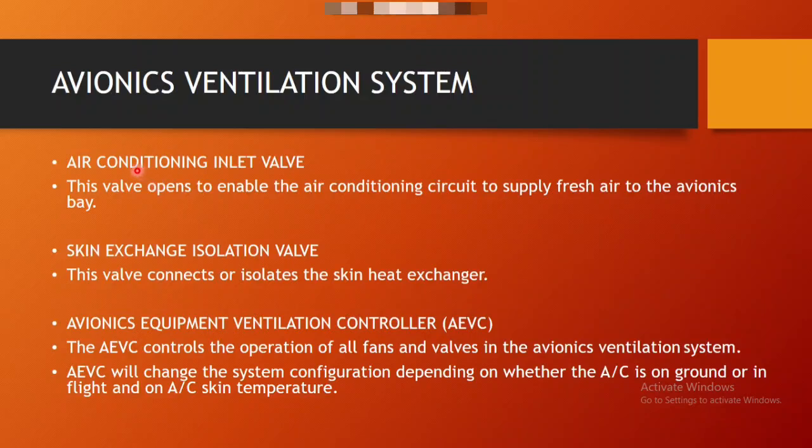Another is the air conditioning inlet valve. This valve opens to enable the air conditioning circuit to supply fresh air to the avionics bay. So once you are using air conditioning, the in-flight air conditioning system will provide this cooling. So this is for that only. Skin exchange isolation valve. This valve connects or isolates the skin heat exchangers. So there is a valve I told you about in the previous slide. So that valve can be isolated from the skin heat exchanger.